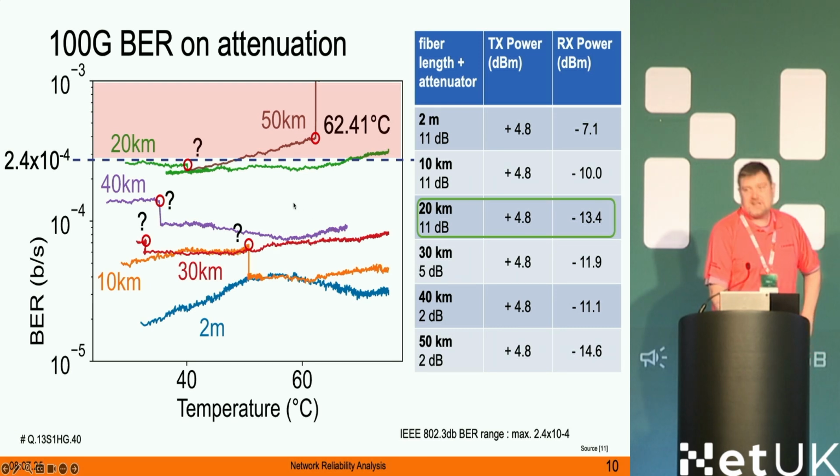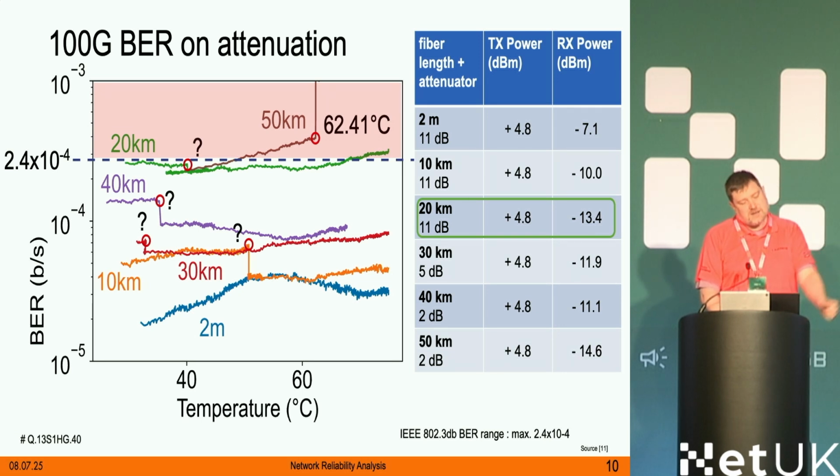The thing is, when the transceiver gets warmer, usually what the transceiver tries to do in its control circuit is to keep a stable temperature on the laser. In order to do this, the laser has to be cooled down as well. Usually you have some elements that really take out the heat, and with that you need more power. So it's investing more power, it's targeting a certain power, and that's the reason why you have this effect that it jumps down a little bit, but it really does not improve. So high temperatures are not a good idea, obviously, but you can see there is an approach trying to keep this stable. And with another transceiver I'm going to show you, it will be more interesting.